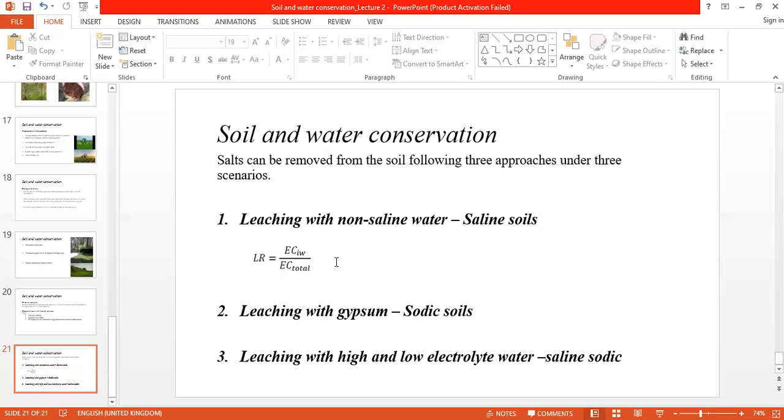First, soil cover will prevent the raindrop impact detachment, and also it will prevent the transportation because it has reduced the velocity with which water is flowing on the slope. So we've seen these measures and we've seen the mechanisms by which they reduce erosion.